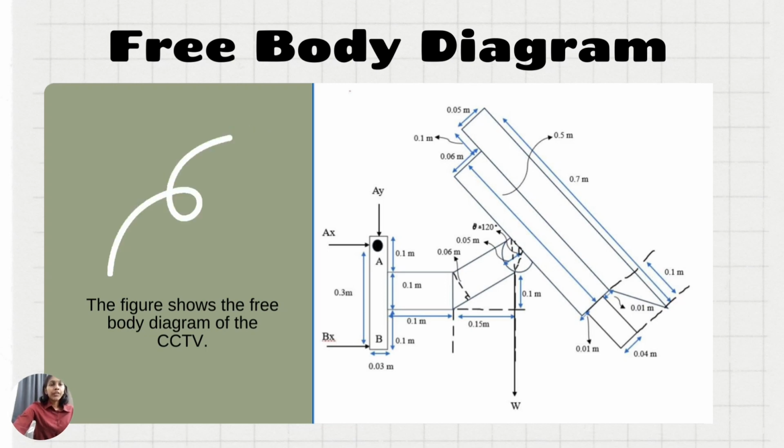So there are three unknown forces. The first force results from a pin support, which is AX and AY. Then we have another force, which is BX. These three forces can be defined using the three equations of equilibrium, which are Fx equal to 0, Fy equal to 0, and moment equal to 0. We can also see the measurements and the weight, which can be used for the calculation of the centroid. After the free body diagram, we proceed to the rigid body equilibrium calculation.